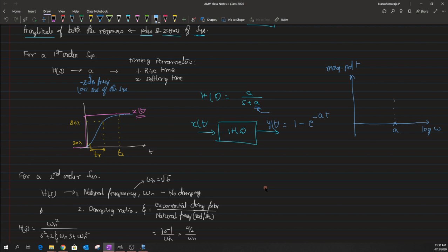When we try to plot the graph, in this case I am not plotting in terms of dB, but rather just in terms of values. So I have a gain of 1 throughout this medium, and till I reach this particular pole location, I assume that the gain from the input to the output signal over the different frequency components remains the same. This is an approximation that we are following here, but in reality it never happens. The signal tends to get degraded, and when it reaches this particular point where I have a system pole, the signal would get degraded to a value of 0.707, which is nothing but 1 over square root of 2.